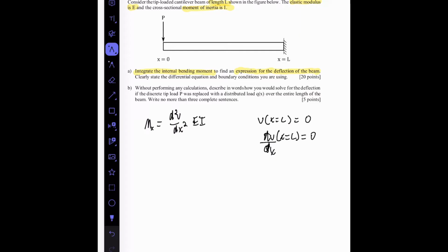So, the bending moment is going to be, if we define our coordinate system as being this, and I'm just defining my sign conventions here. The moment is going to be this load P, and it's going to be negative since it's pointing downwards, times the distance x at any point along this beam. So M of x is just going to be equal to negative Px.